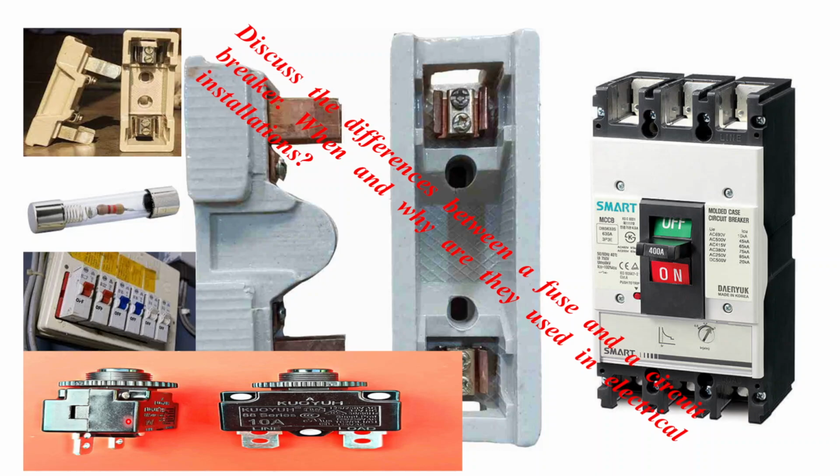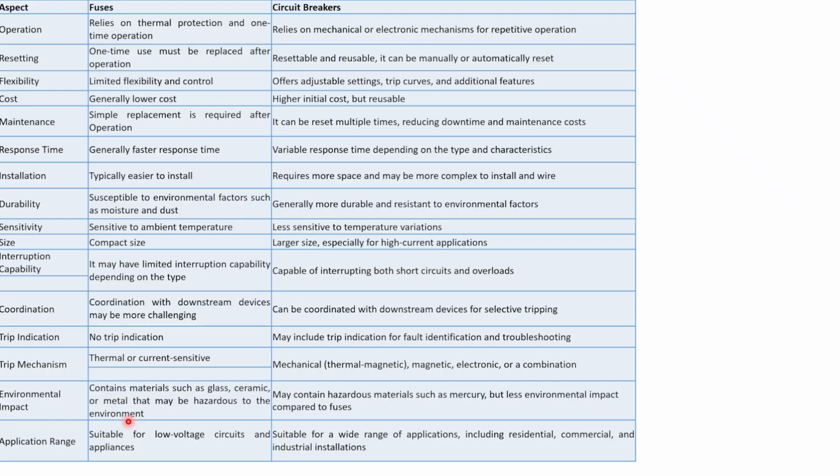So in conclusion, both fuses and circuit breakers play a crucial role in electrical installations by providing overcurrent protection, but they differ in terms of operation, characteristics, and applications. The choice between them depends on factors such as cost, complexity, flexibility, and specific requirements of the installation. So this is the difference between the fuse and the circuit breaker.